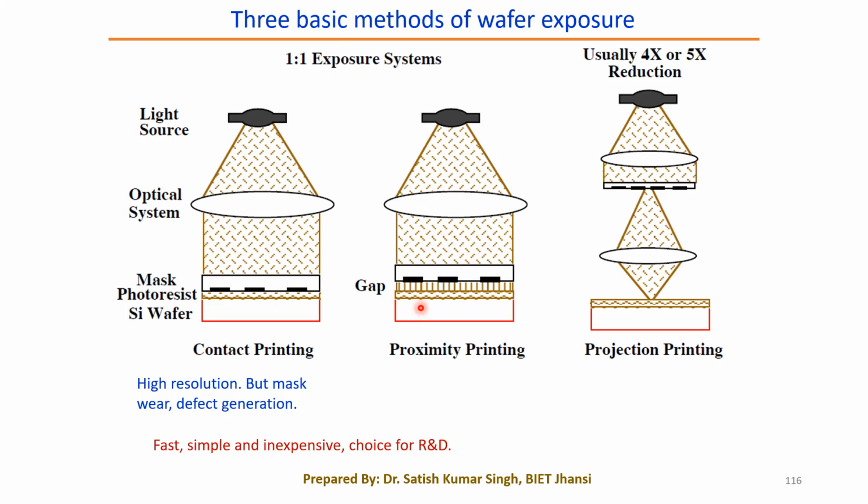exposure mechanism. So this proximity printing is going to reduce the disadvantage of contact printing, which has the hard contact and a large defect density because of it. In proximity printing, this disadvantage can be overcome, but still the problem is the resolution is not that high.